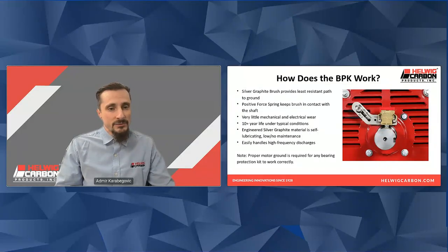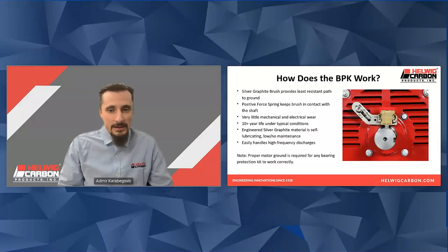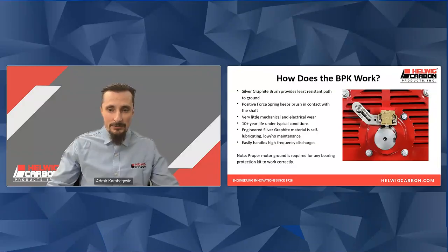The engineered silver graphite material is self-lubricating and doesn't need any kind of maintenance. These kits also handle high frequency discharges. We should note that our BPK, or any bearing protection kit device, won't properly function if the motor ground is not properly set.